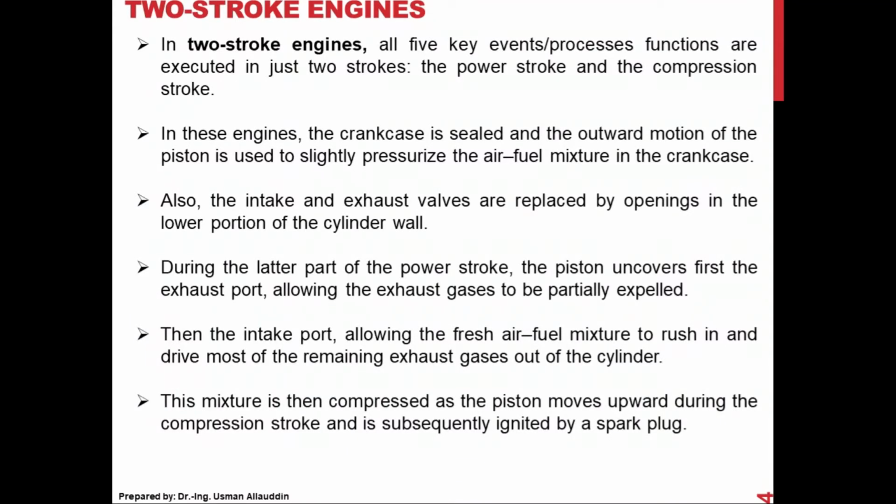Now let's discuss two-stroke engines. If you recall, students, we also discussed this in the course of thermodynamics. In four-stroke engines, let's suppose we have the compression stroke first. In the compression stroke, intake and exhaust valves are closed. The piston moves from bottom dead center to top dead center, the pressure increases and the volume decreases. During the compression stroke, intake and exhaust valves are closed.